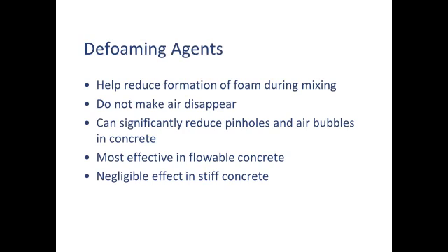Now, I had mentioned that Forton has other specialty admixtures added to it to improve its properties, and one of those is a defoaming agent. There are a few commercial defoaming agents on the market. They're generally sold as powders to be used in self-leveling overlay mixes, where you're pouring on a thin layer of concrete that self-levels on its own, and you don't want bubbles in it. Defoaming agents help break up the foam that's generated as you mix concrete.